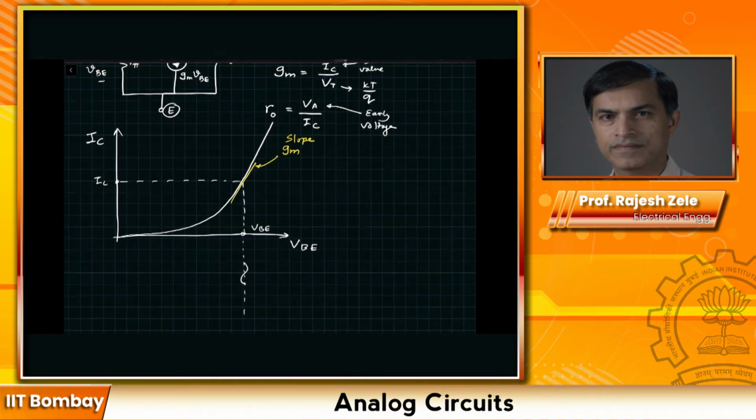One important aspect I would like you to think about is, would you see an inversion over here? The answer is no, there will not be an inversion, and let me explain why. The small signal VBE, which is over here, is changing in this fashion. If VBE increases, does the collector current increase or decrease? That's the first question. The collector current will increase. Hence, there is no inversion when we plot the small signal characteristics between VBE and IC. So what we expect here is characteristics that look like this.